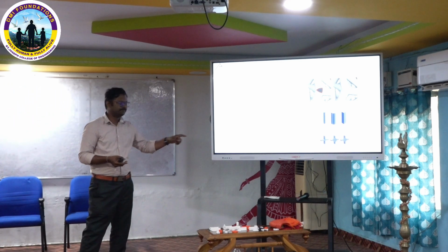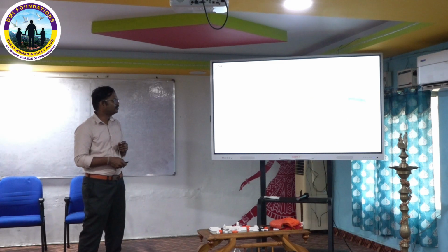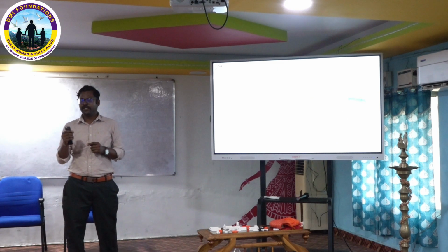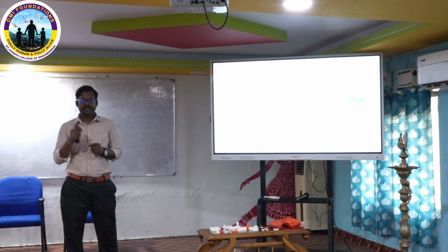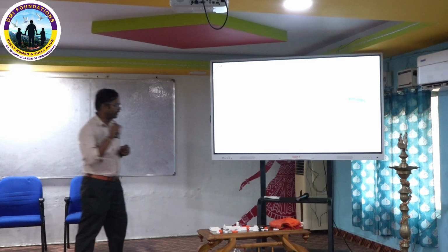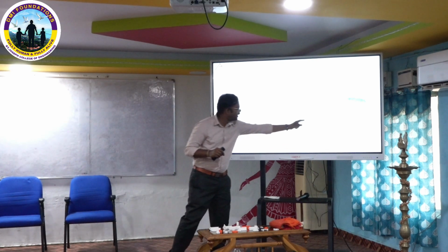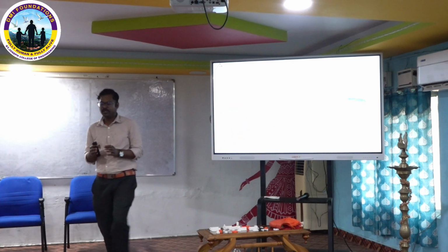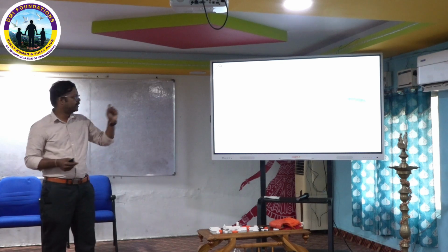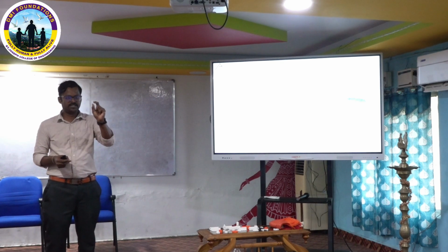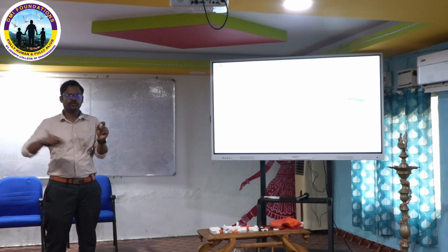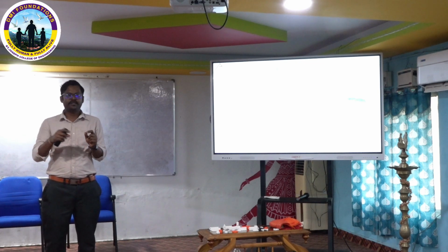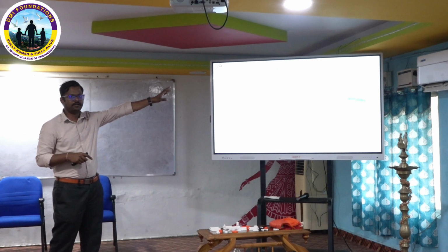Then post processing complexity. Actually, when you do post processing, you need to get a graph, right? The stress and strain value. You have to select a particular point, not the full component; the stress and strain curve, you can't get that. You should select only one point or one mesh, and in that mesh you need to plot the graph.